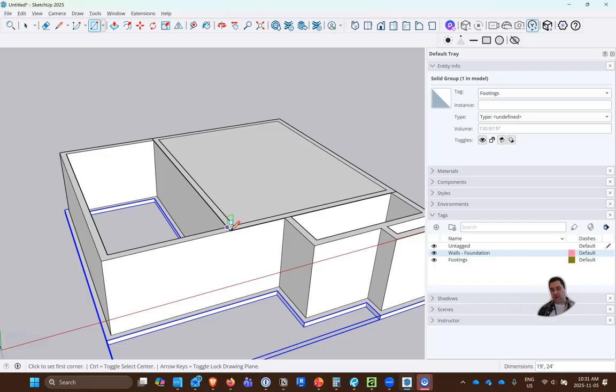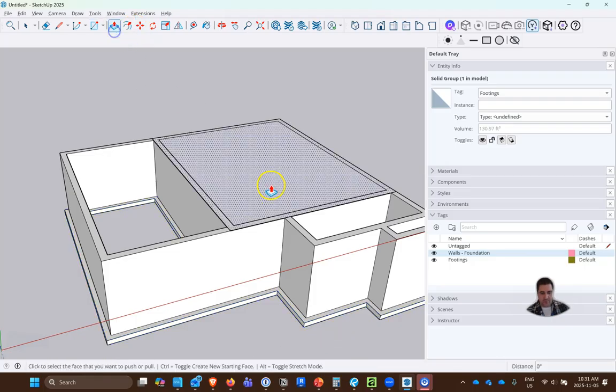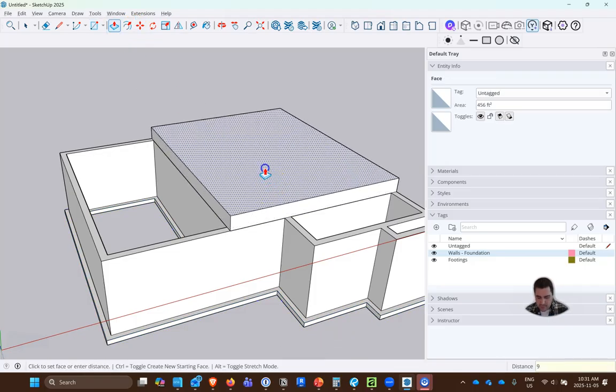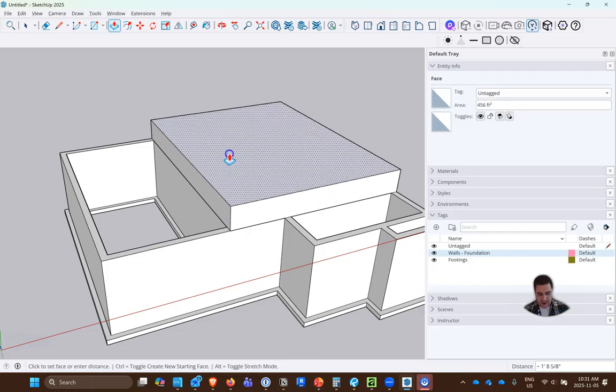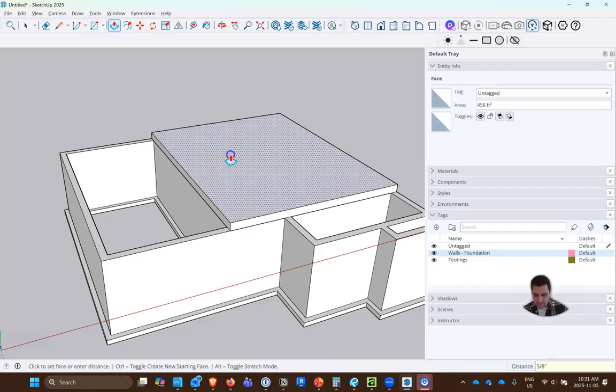So I just drew a box on our wood floor area, and we're going to go up 9 1/4. And I'm going to remove the 4 I put in there. The next part is going up with our subfloor. Our subfloor is 5/8, so we're just going to go up another 5/8 of an inch. That'll be our total thickness of our floor. And again, I didn't have to do math because we put those numbers in separately, which made it a little bit easier, right?